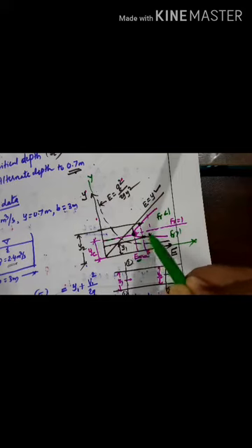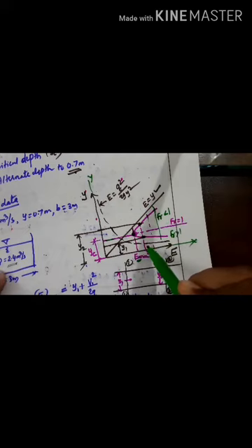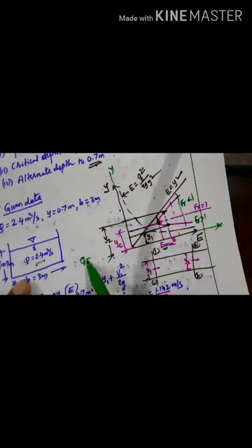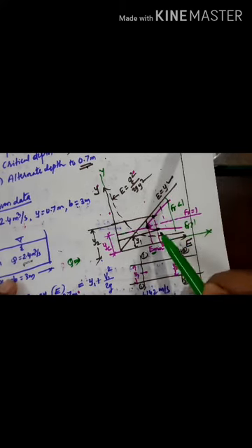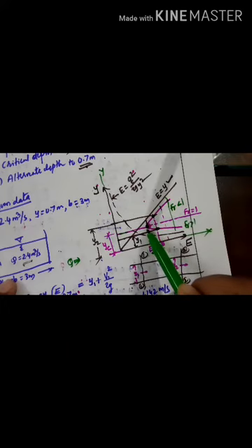Leaving that point, wherever you take points on the curve, for the given discharge you will get two depths. This means the discharge q, which is a constant, can be passed in two different depths. Those depths are called alternate depths or sequent depths. This we have discussed in the specific energy curve.